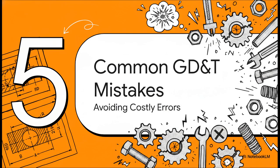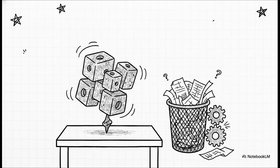Finally, Section 5, Common GD&T Mistakes. Because, let's be real, the gap between engineering theory and shop floor reality is where things usually go wrong. And trust me, they go wrong often. Industry experts from Sigmetrics frequently point out that the #1 mistake engineers make is just overcomplicating their designs. They'll choose non-functional datums just because they're super easy to dimension in CAD, entirely ignoring how the part actually mates in its final assembly out in the real world. They'll also select unstable features, like tiny warped edges or rough cast surfaces as a primary datum. That just makes the part wobble all over the place during inspection. Doing this is a surefire way to take a perfectly good functional part and make it look like expensive scrap on an inspection report.